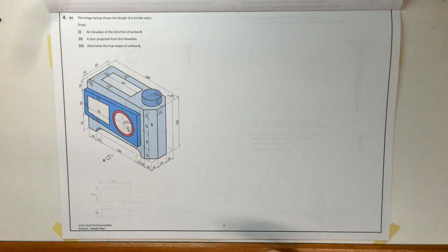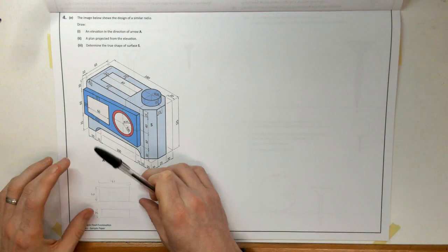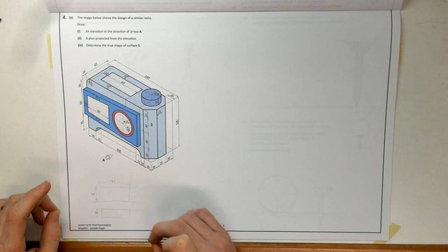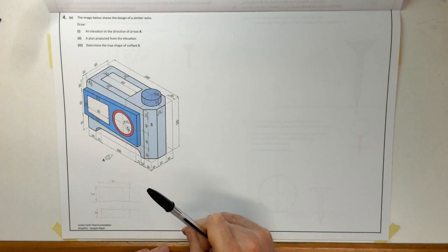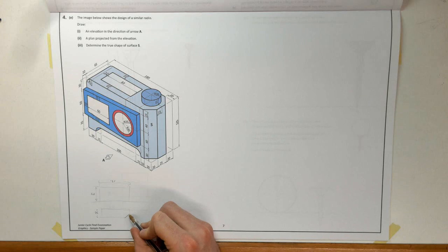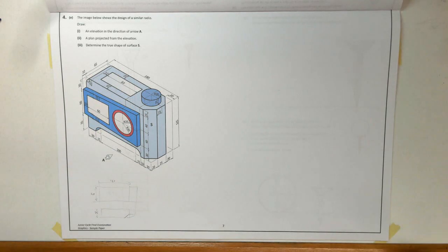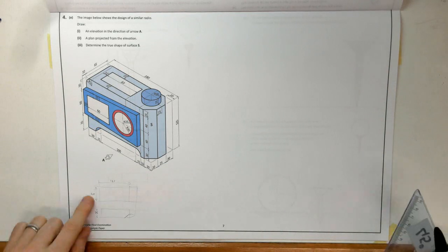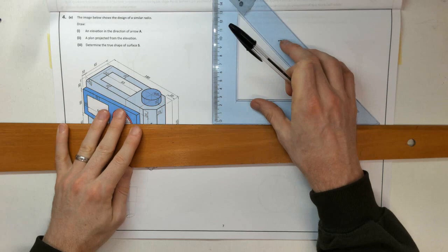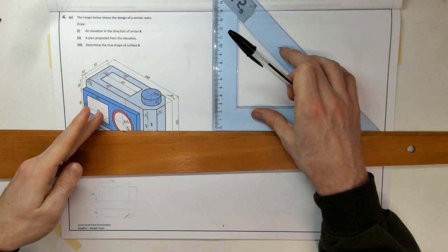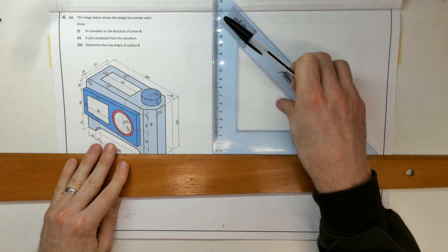Important to do that just to make sure that we set up our question so that it fits on the page. There's no end elevation in this question, so we don't have anything either side of it. We will be doing a bit of a rotation for the true shape of that, so that will be coming out here. So once I've got space to the right of that, it should be fine. So 140 down, let's come down a little bit more than that just to fit it in. That's 140, 160, 170 down from the top.